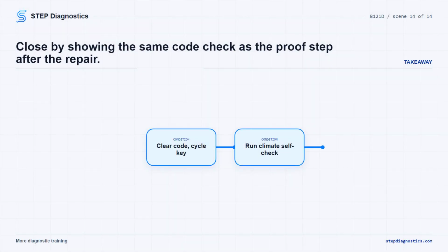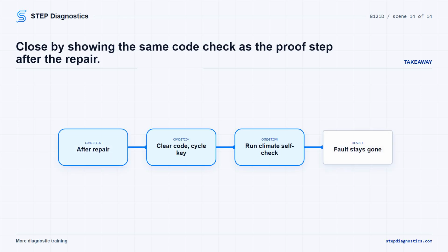After any wiring repair or supported component replacement, verify the repair by going back to the first check. Clear the DTC, cycle the vehicle OFF and on, run the climate control self-diagnostic, and confirm the fault does not return. The key is to let the circuit tests tell you whether the problem is power feed, sensor COM, HUM data, HUM CLK, the sensor, or the climate control unit.